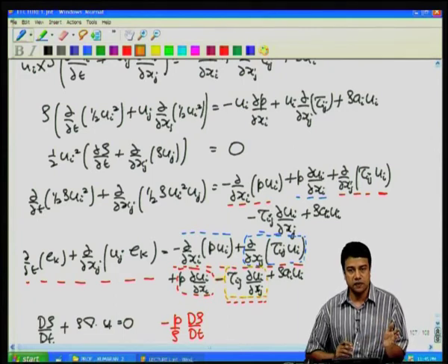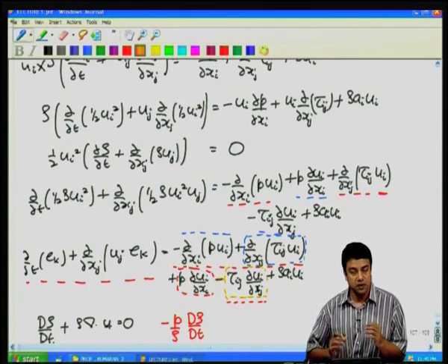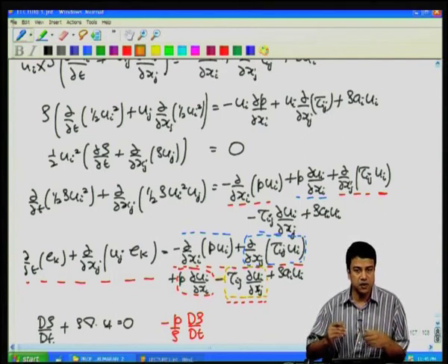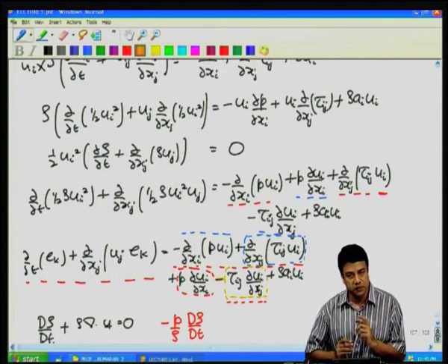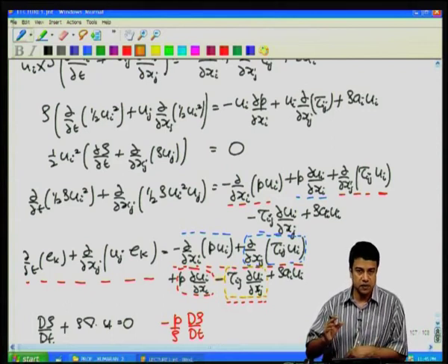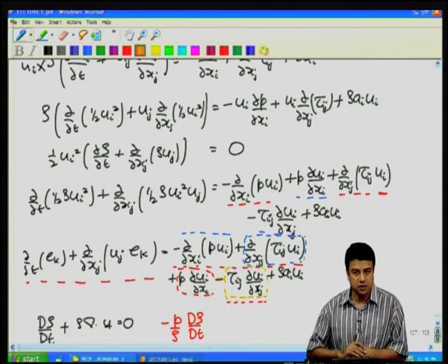The pressure gradient, for example, which you apply between the ends of the pipe in order to force fluid through it, is because the energy is being constantly dissipated within the fluid into heat energy due to this dissipation term. Happens only for a viscous fluid. If the viscosity were 0, then I just have the Euler pressure term, which was reversible. However, all fluids have a non-zero viscosity, therefore, they always convert energy from mechanical energy to heat energy, and that causes dissipation in fluid flows.